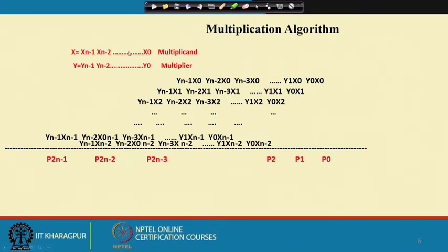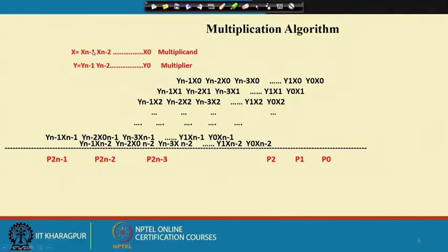The bitwise multiplication operation is performed here in binary multiplication. Okay. Now the bit y0 of y, the multiplier, will be multiplied with each bit of x, and that will be written in the first row. Here one bit multiplication is nothing but the ANDing operation, right.